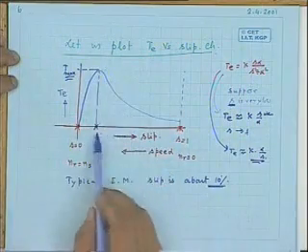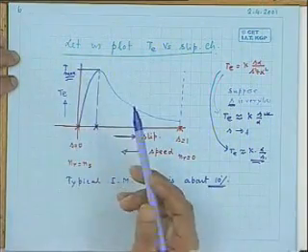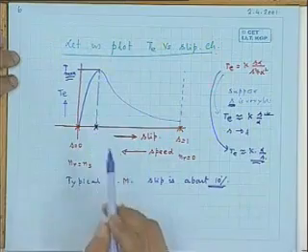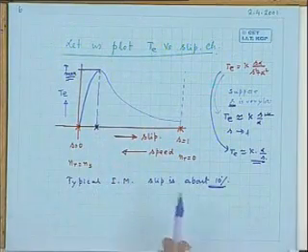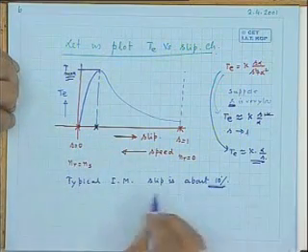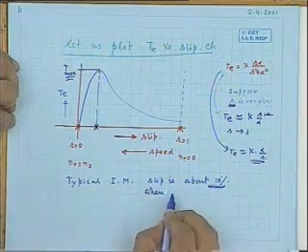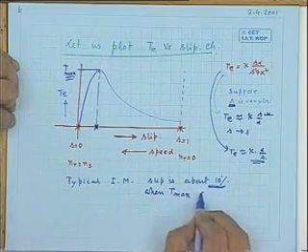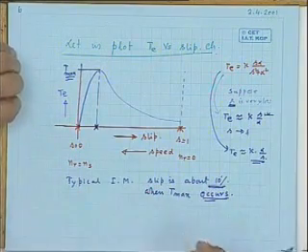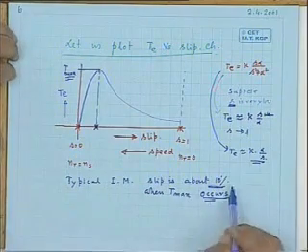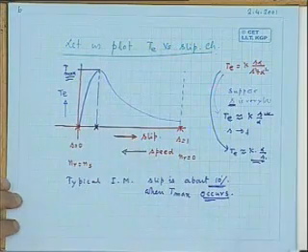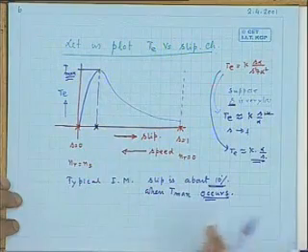This is the torque versus slip characteristic. As you can see from the curve, there will be some maximum torque the machine can develop, and that occurs at a particular value of slip. For a typical well-designed induction motor, this value of slip is about 10% when Tmax occurs. Not very strictly 10%, it could be 8%, 12%, around 10%. This will be the torque slip characteristics of the induction motor.